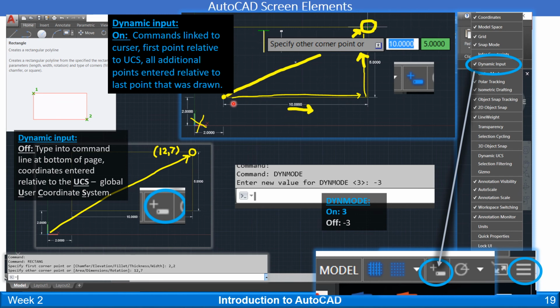So let's say you're trying to draw a 10 by 5 rectangle. You're going to click on the first corner of that rectangle, and in dynamic input, your second corner is going to be at over 10 and up 5. So you're measuring it relative from that previous point. How that differs when dynamic input is off.